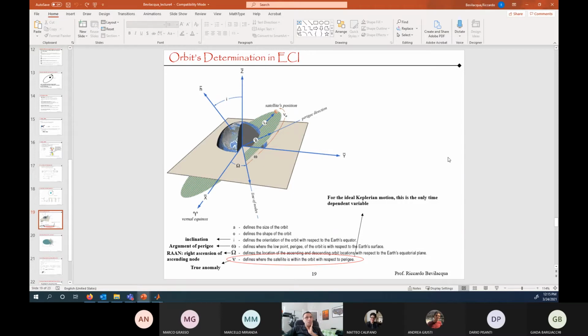And as with everything that we have seen for attitude, these perturbations could be bad, a disturbance, but they can be exploited. So again, this goes a little bit beyond the topic of the class. But for example, the oblateness of the planet at the poles, what we call J2, the fact that the Earth is a little bit like a ball that has been squeezed at the poles, north and south, creates a precession in the right ascension of the ascending node. So your orbital plane rotates, the big omega changes. And that effect is a disturbance, but it's also exploited for sun-synchronous orbits.